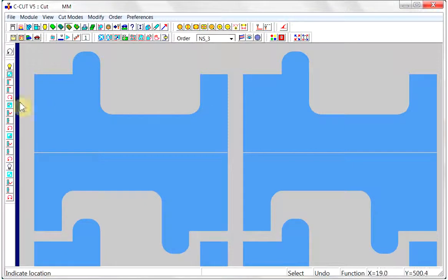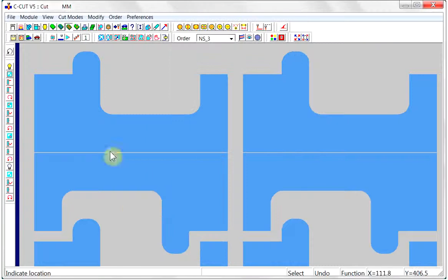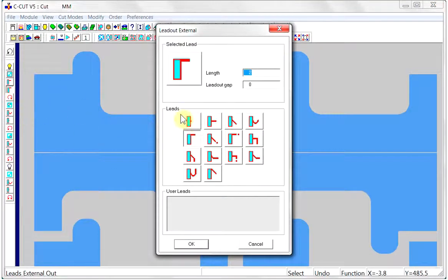Please note that the common line cutting reduces cutting travel and reduces the number of piercings. It is great for oxyfuel and laser, but for plasma it should be taken into account that only one side of the plasma cuts straight. Please note the quick correction of a cutting mistake.